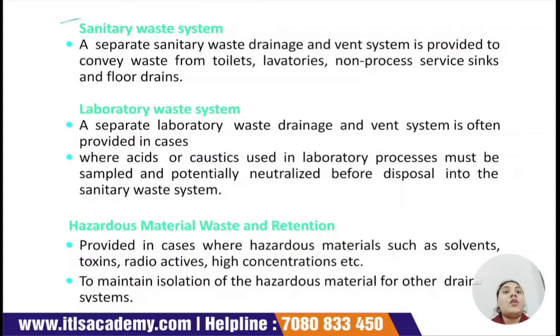Now moving to the sanitary waste system. So now comes the third type, that is the sanitary waste system. How to dispose of the sanitary waste? There is a separate sanitary waste drainage and vent system in any pharmaceutical plant, and their work is to convey the waste from toilets, lavatories or non-processed services, sinks and floor drains.